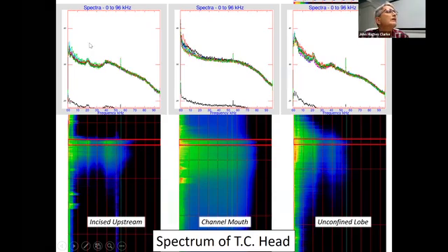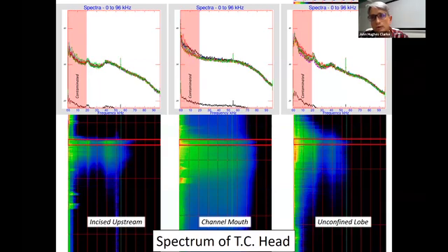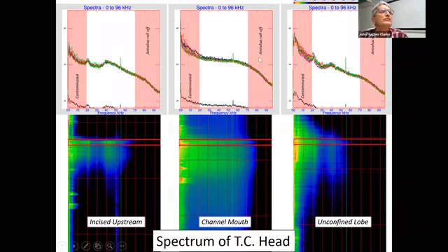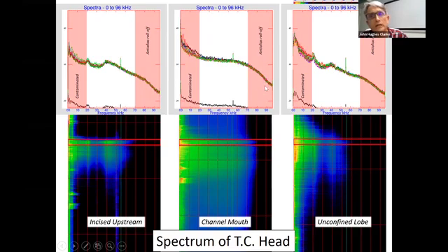In each case, what we're seeing up here is the spectra while the head went by. These are in dB. I haven't shifted it for calibration, but that's the frequency. We have to remember we can't use less than 20 kilohertz. Also, because of the design of the anti-aliasing filter, there's a roll-off. The Nyquist is up there at 96, so you're rolling off from about 70 kilohertz onwards. So we've really only got a bandwidth of about 50 kilohertz, 20 to 70.